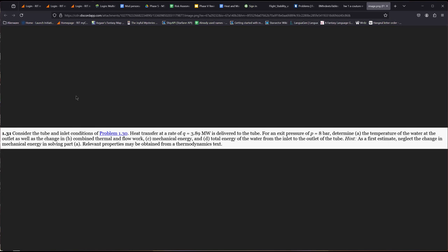I'm just going to read off the question so you have time to read it on your own or listen to me. Consider the tube and inlet conditions of problem 1.30. Heat transfer at a rate of 3.89 megawatts is delivered to the tube for an exit pressure of 8 bar. Determine the temperature of the water at the outlet as well as the change in combined thermal and flow work, mechanical energy, and total energy of the water from the inlet to the outlet of the tube. A helpful hint is that as a first estimate, neglect the change in mechanical energy when solving part A.